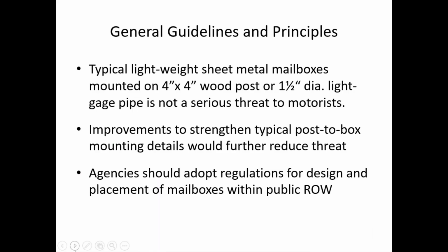So the AASHTO Roadside Design Guide talks about some general guidelines and principles, and they do have a lightweight mailbox mounted on 4-inch by 4-inch wood posts or 1.5-inch diameter light gauge pipe that's not considered to be a serious safety issue for motorists. And they recommend that agencies adopt regulations for design and placement of mailboxes within the public right-of-way. This can be a liability issue both for the property owner, but also for the road agency.